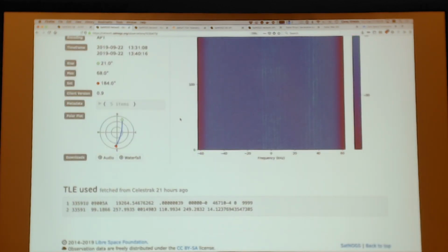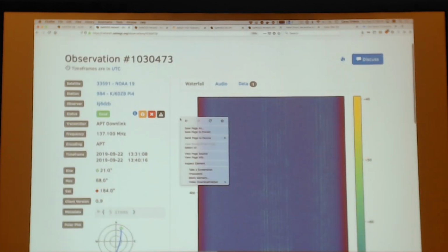One more question. Apparently your software and SBR software is smart enough so that when it does a Doppler shift of the receive frequency, somehow it does not phase screw up the data. In other words, a lot of satellite operators are running Doppler correction and they don't decode anything, because every time the radio steps, there's a phase transition in the receiver and you just lost. Yeah, the question is the resolution of the Doppler shifting versus not being able to decode because of changing the phase.